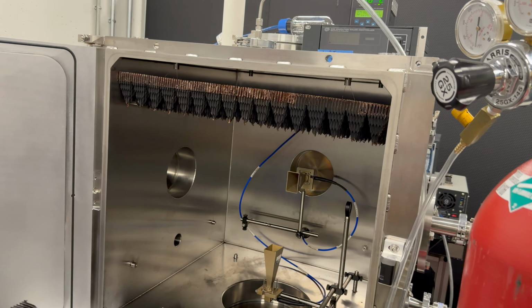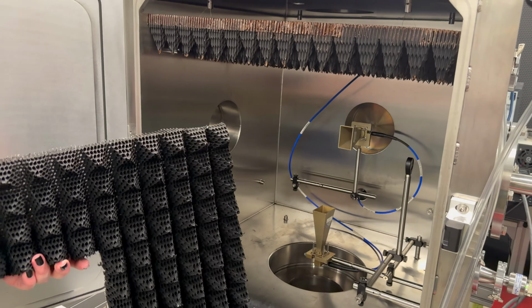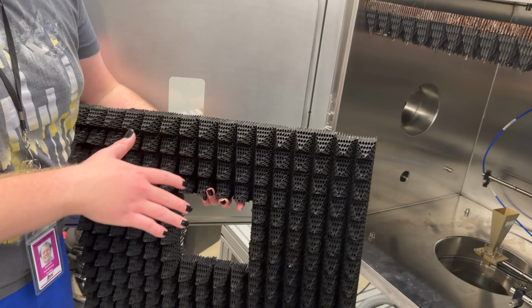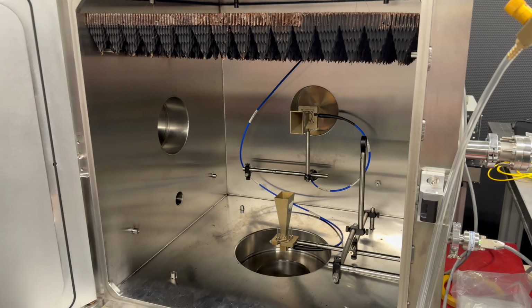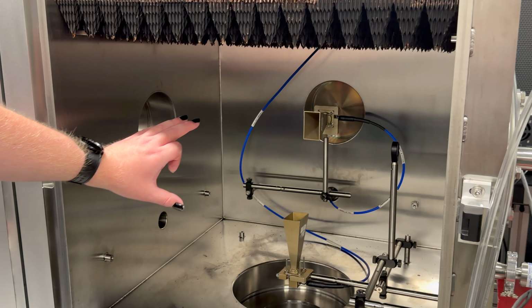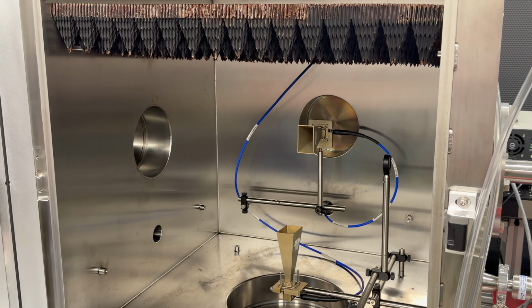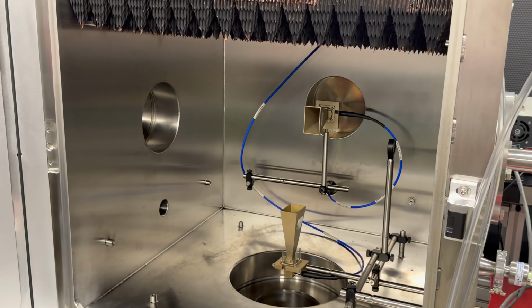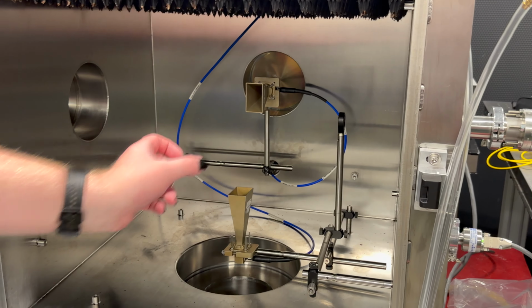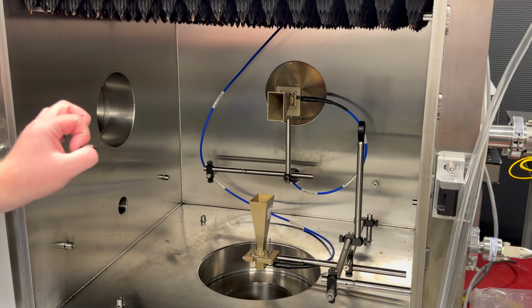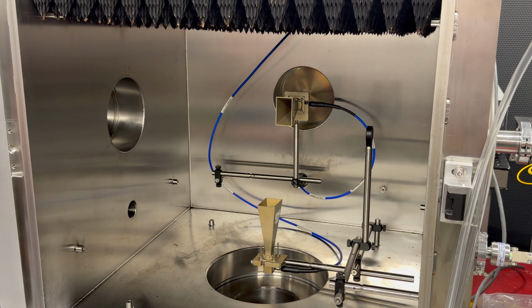So you can see here the internal setup. These absorbing panels are used to lower the noise floor that happens when you're using the CMS system coming out of these gain horns here. So we'll have a receiving and transmitting horn. On both sides, we have these microwave absorbing panels, as well as a 200 millimeter lens that we used previously in order to decrease the spot size that we're able to reach, which increases the intensity.